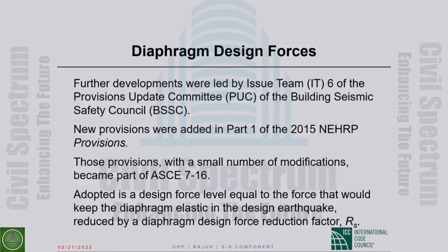That is true of the redundancy provision. So it is not that I switched to ASCE 7-10 across the board, but for the building separation provisions, I definitely switched to ASCE 7-10. Diaphragm design force, ASCE 7-10 and ASCE 7-05 are the same if you are looking at section 12.10.1. So it doesn't matter whether I say 10 or 5.